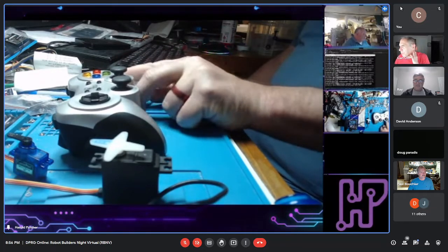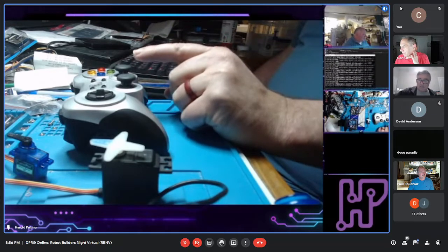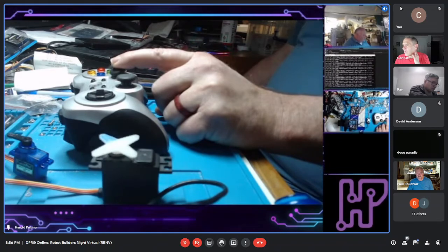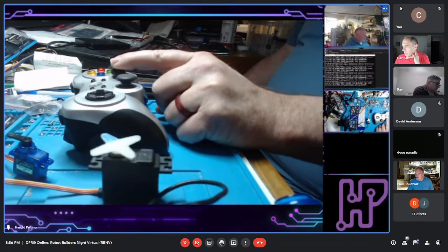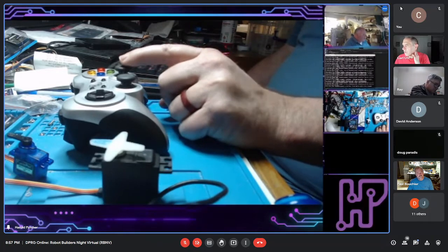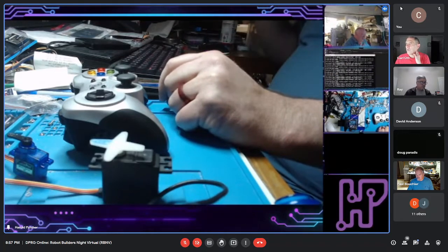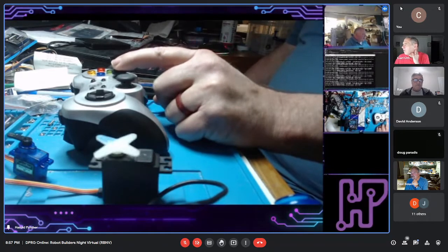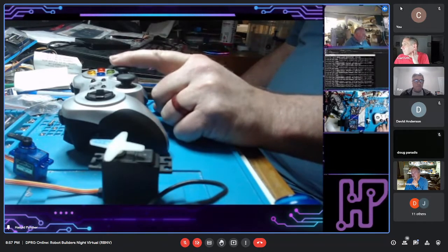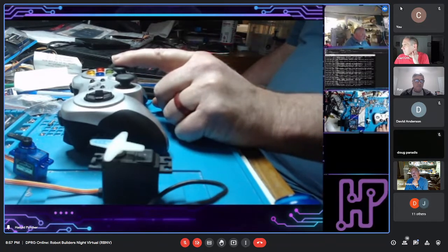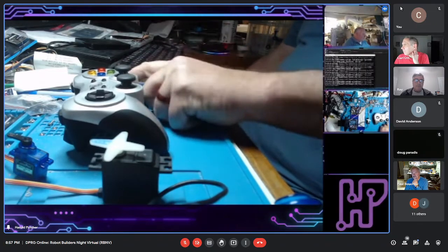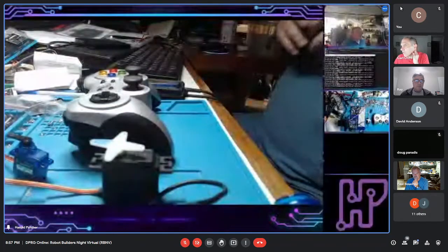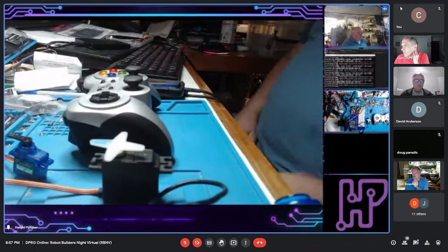And I might leave it in the degrees, or I don't know at the moment, but listening to everybody that's here, they were asking me, why would you do that? I want to make this a vector. So a vector gives me a velocity and a direction, right? So even though with continuous I got on or off, I want to code it so I have a choice to move slowly or fast, and from the teleop stuff, translate the plus and minus noise into a velocity and a direction. Then once I send that down to the Ackerman node, have the Ackerman take that velocity and direction and figure out what to do with all 6 wheels for turning and all that sort of stuff.